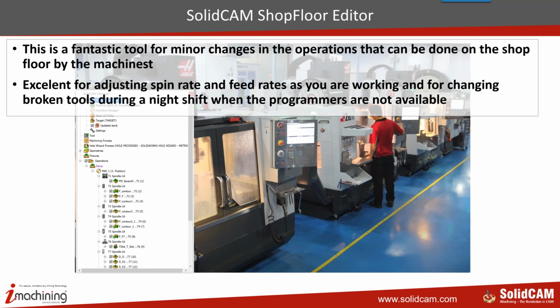Let's say he's listening to the machine, there's a little bit too much vibration, he has enough experience, he just wants to make some changes in the feed rates and the spin rates, and he can do that all by himself. Notice this program is just for making the edits, the small minor edits that he needs.